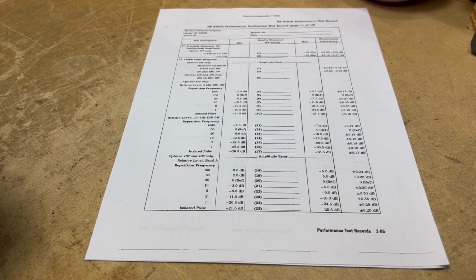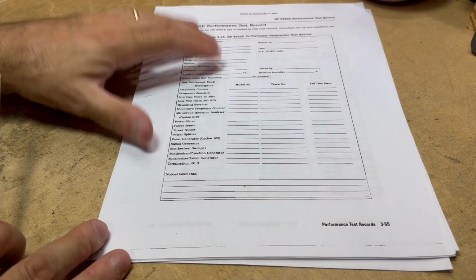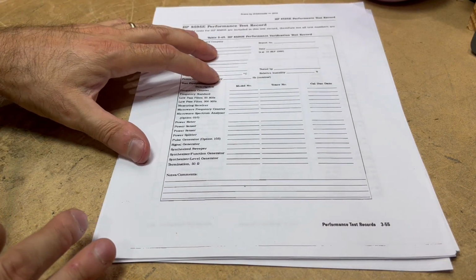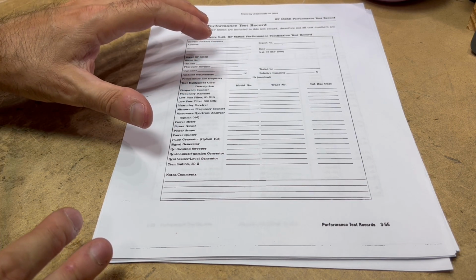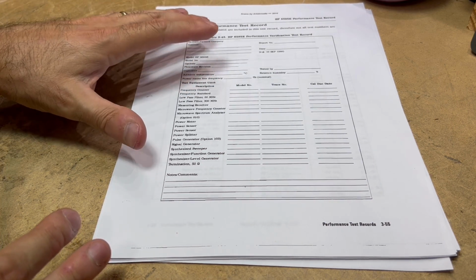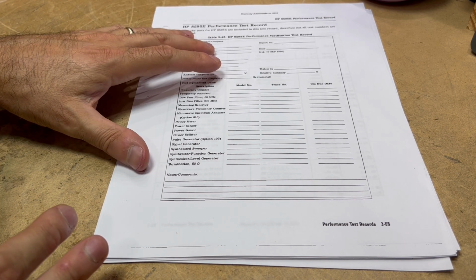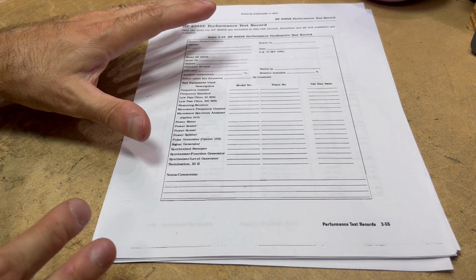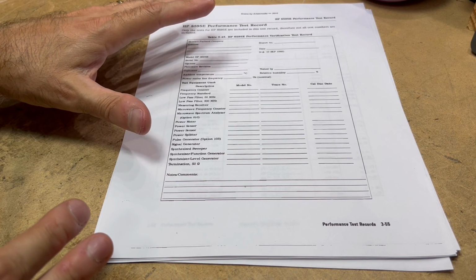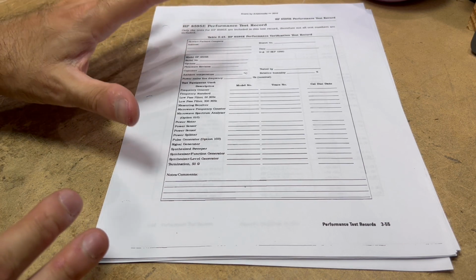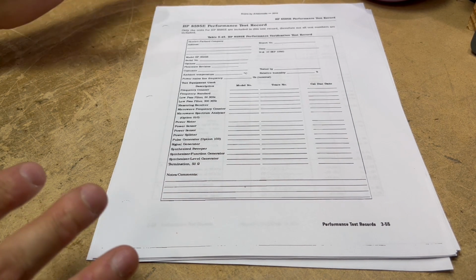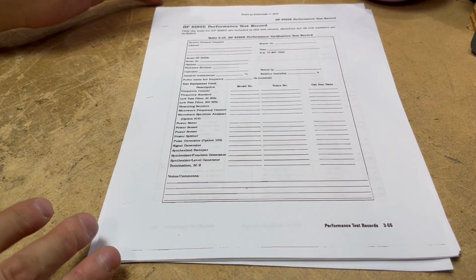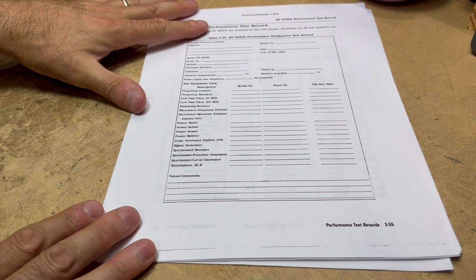So the big thing to take away from doing the cal section is that all of the recreating of the calibration constants for the frequency corrections and the attenuator cal error, all of those things that we did and made changes to the instrument, the spectrum analyzer is still performing within the specifications of the cal record.